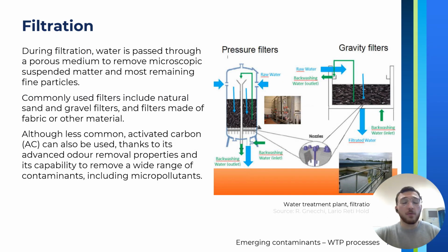Filtration is an ancillary step of wastewater treatment, often included in many wastewater and drinking water treatment plants. During filtration, microscopic suspended matter, most remaining fine particles, and even dissolved contaminants are mechanically removed by a porous medium. Commonly used porous media include sand and gravel in natural filters, filters made of fabric, as well as activated carbon, an exceptional porous material for the removal of a wide range of dissolved contaminants, including emerging contaminants and other micropollutants.